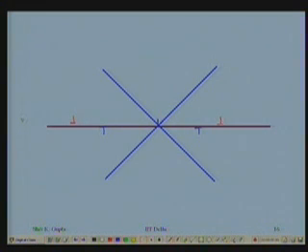However, when I go in a region just above this, if I have a dislocation of this sign, there would be an attraction between this and this. So what does this cross represent? This is a region around the dislocation line, at an angle of 45 degrees from the slip plane.